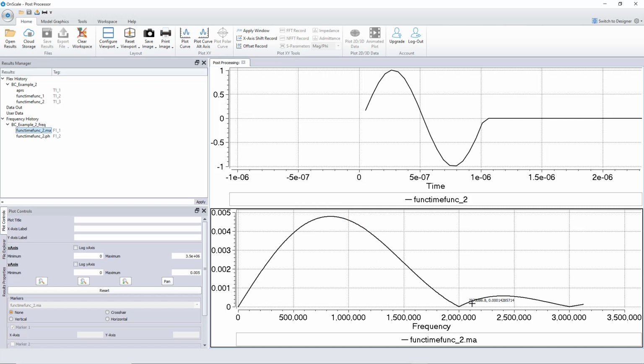So we see that the sine impulse has several harmonics. Sometimes this is a problem, and that's why generally wavelet type of functions like the Ricker wavelet are much more used, because they have no higher harmonics like that. Okay, so now let's come back to the PowerPoint and let's continue. Let me give you a few examples of other types of forcing functions.